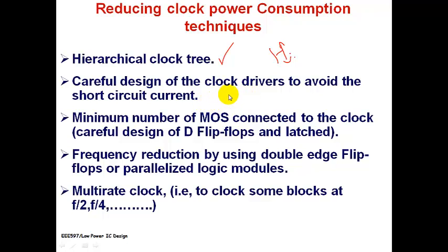And careful design of the clock drivers would be the next thing. What is this for? The short circuit current we will have in the clock drivers. Whatever inverter I have, there should not be any short circuit, and it should not itself be consuming power.